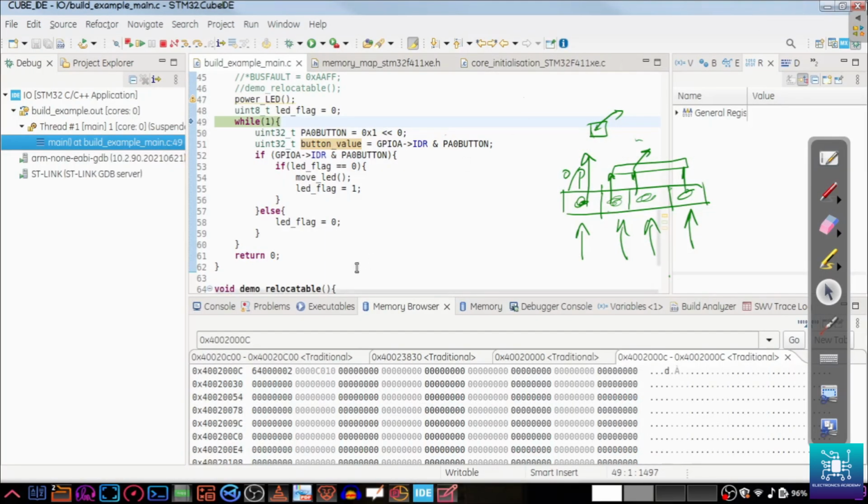When you do it in the interrupt method, the method is entirely different. When you press the button, it raises an interrupt and you go through there. You don't check the button here. We will see that during the interrupts segment, where we'll configure this button to the interrupt pin as an interrupt. So the mechanism is going to be entirely different, but in our case here, we are doing it in the poll method.